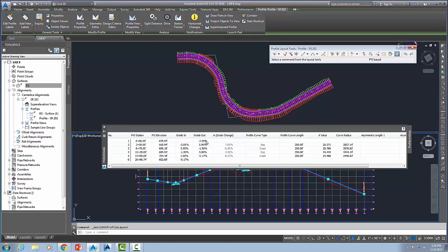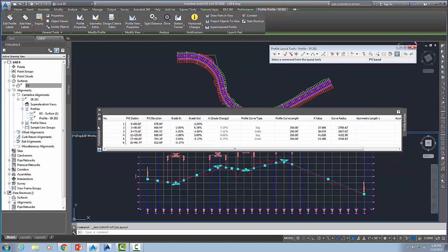So what I first want to do is under station 3 plus 50, change that percent grade up a little bit. So I'm going to bounce that to 525. Okay, and that made a change here. Now we're going to see that it's not making an instantaneous change. We're going to have to rebuild this, but you'll see a change happen once we kind of get it done. So I'm going to move this up, but you will see changes occurring down here.